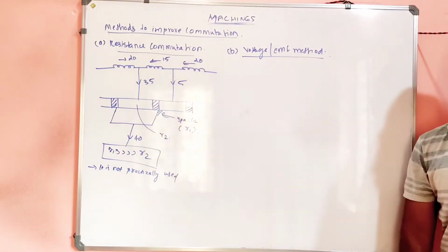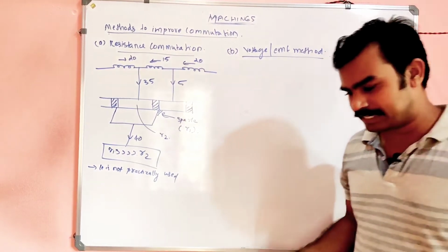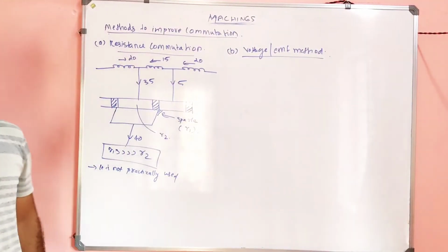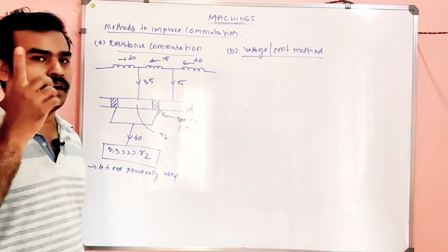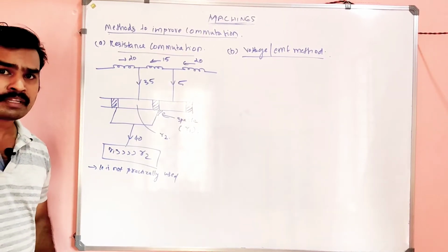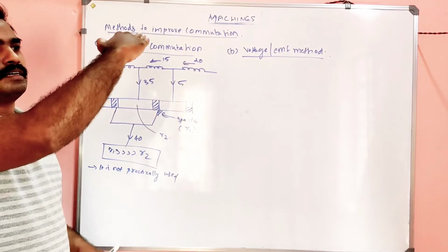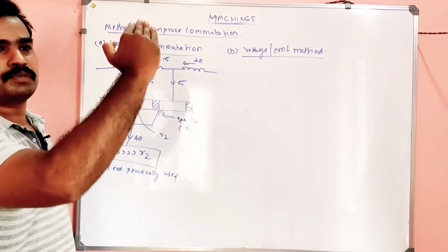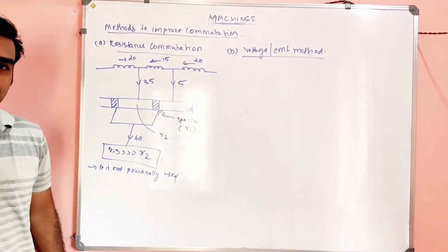Very simply, you can say that it is the armature reaction. That's also an acceptable answer. But strictly speaking, it is the cross magnetizing effect, not the demagnetizing effect, my dears. The cross magnetizing effect is a very big problem, because that is the reason for the tilting or alignment of magnetic lines of force in a not normal manner.